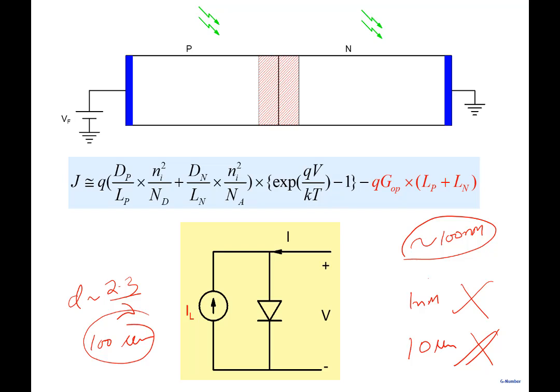Now, if you go back and look at the derivation of p-n junction, most of you are familiar with this part here. J equal to Q Dp/Lp ni square and all that, that is there here. Now, all this derivation that is done assumes there is no optical generation rate. So all we need to do is go back and look into this equation. Let's say the continuity equation, del p by del t is 1 over q del Jp by del x plus G minus R, like that.